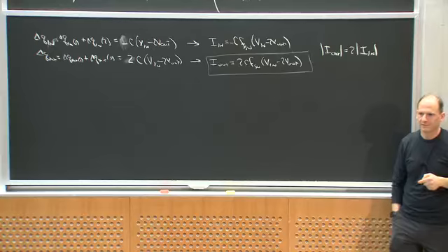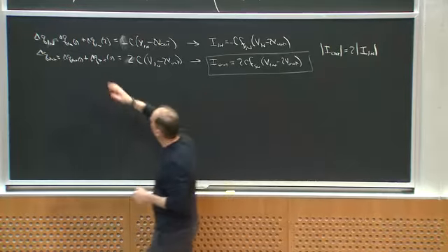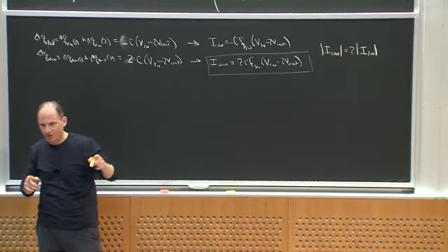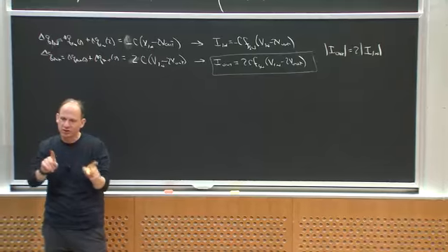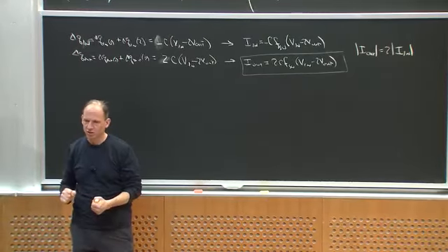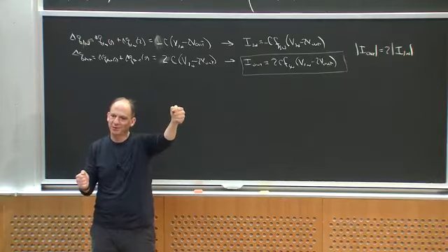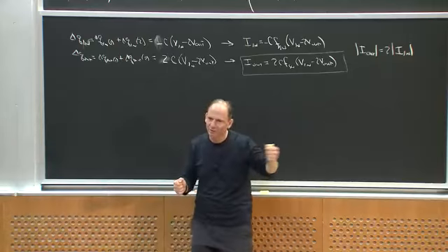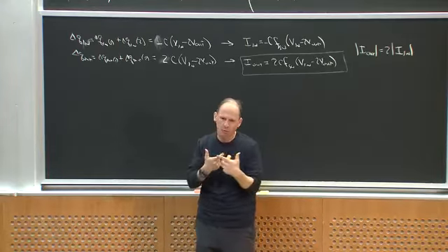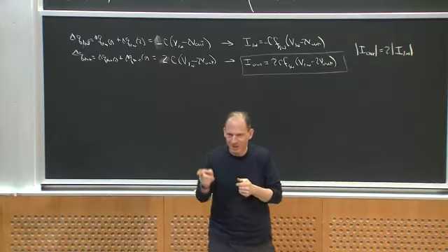Yeah. Is this assuming a 50% duty cycle? That's a good question. So long as the intervals are such that I fully charge and fully discharge in each subinterval in state 1 and state 2, the actual duty ratio doesn't matter in this mode of operation. The only thing I've assumed is that I'm waiting long enough in state 1 for the capacitor to get to its final voltage, and I'm waiting long enough in state 2 for the capacitor to get to its final voltage. As long as I've waited long enough in both states, what their actual fraction of on times are doesn't matter. We'll come back to that shortly.